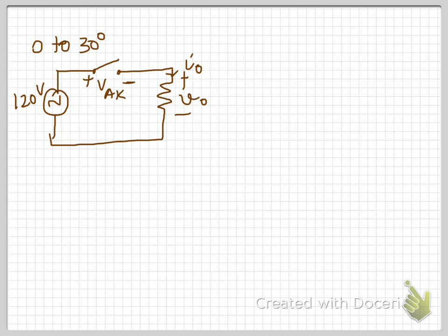Now if you look at this circuit diagram, you can write the values in here. It's an open switch, so VO is 0, IO will be 0, and this will equal VS, because this side is connected to the source and this side is at 0 volts. So the voltage at this point with respect to this point is VS.